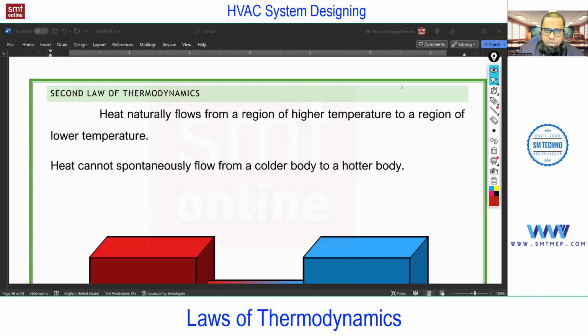Heating. So now the question is, on what basis can you conclude this? How can you say in summer a cooling system is required? In summer, outside temperature is more, so heat transfer to the inside is more, so we need to extract the heat from the inside to outside. So with the direction of heat only we can consider that a cooling system is required. The direction of heat in summer is from outside to inside, because outside temperature is high and inside temperature is low. So heat flows from high temperature to low temperature. Then only we can conclude that the cooling system is required in summer.